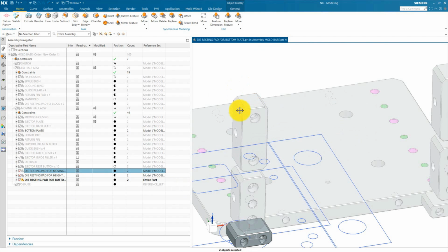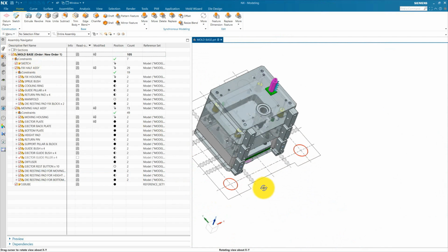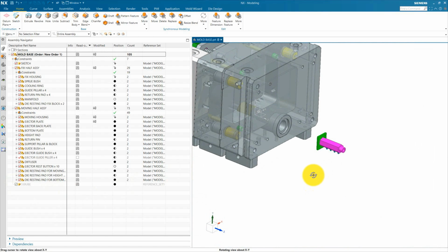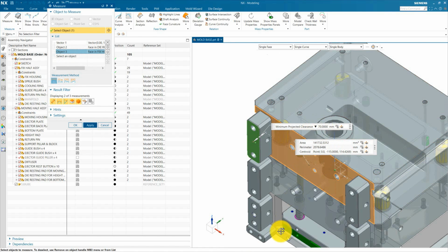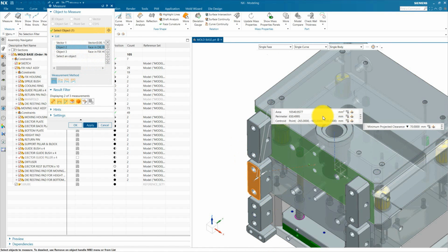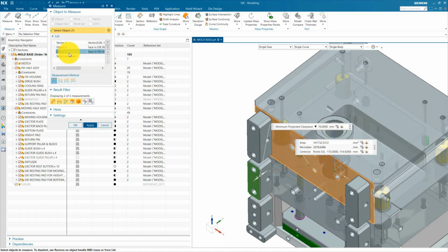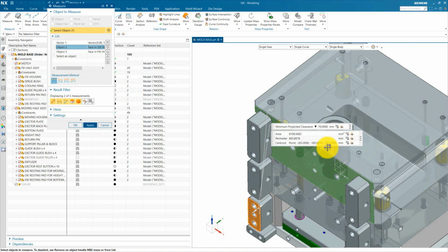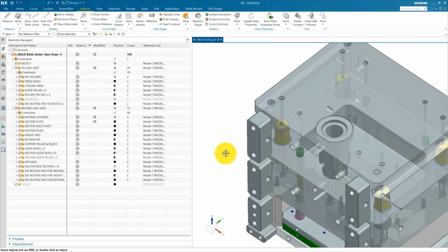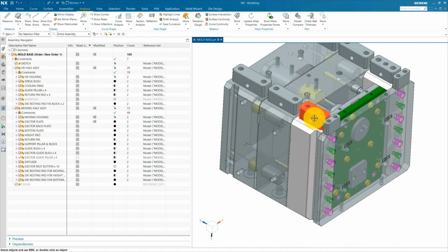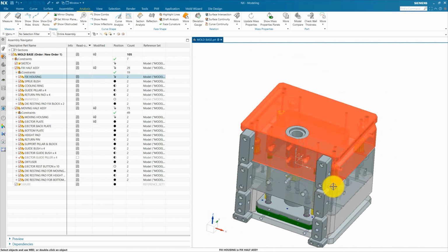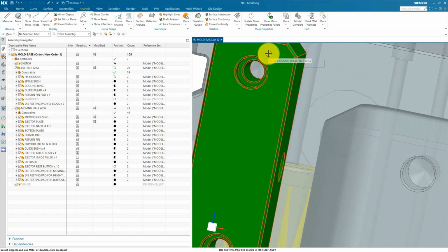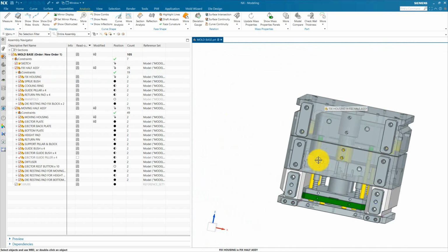These are 70 and 70, but the common thing in all die resting pads is the height from the ground. This ground here we use 70. From this to this the height is 70 in every one. For example, this is also 70, and you can also select this, it is 70, and you can also select this, these are 70. So this is important, all are equal. Our fixed housing, moving housing and height pad we provide a hole, but in that case it is not necessary to provide a hole. The next step is we need to add a threaded hole for our die resting pad inside the fixed housing, moving housing, height pad and bottom plate.